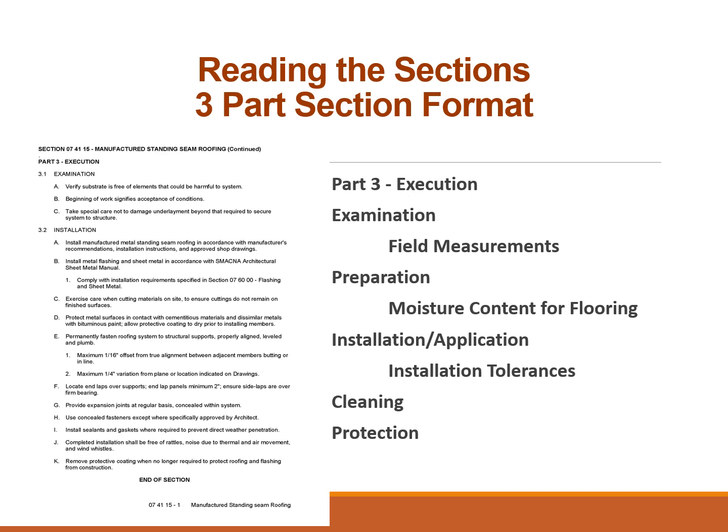You might also want to tell them that we want field measurements taken so they're not cutting things into small pieces in the field, which in some cases is acceptable. In this particular situation, you want them to have the field measurements as it's relevant, especially for the valleys and the eaves and the other specialty elements.